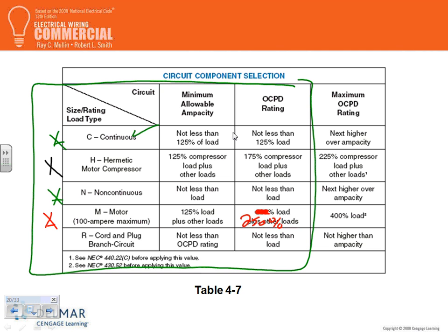If you have a chiller, this is your chiller. A chiller, guys, the same thing, continuous load, and the overcurrent device most of the time is 175 percent of the load. So, any question, guys, about these? I'm going to take a few examples when you come back.